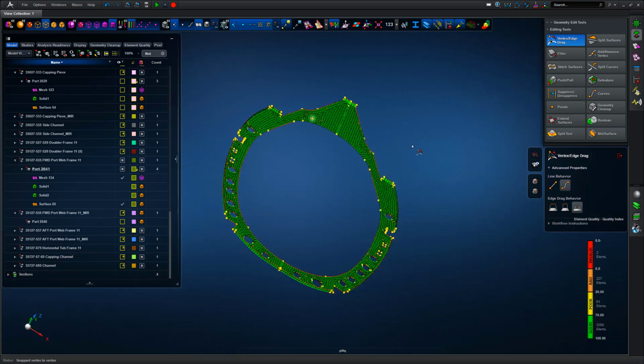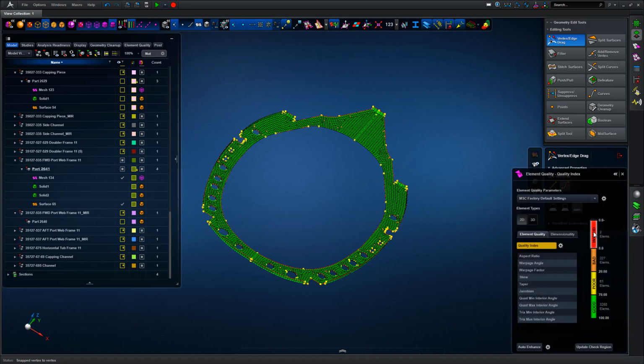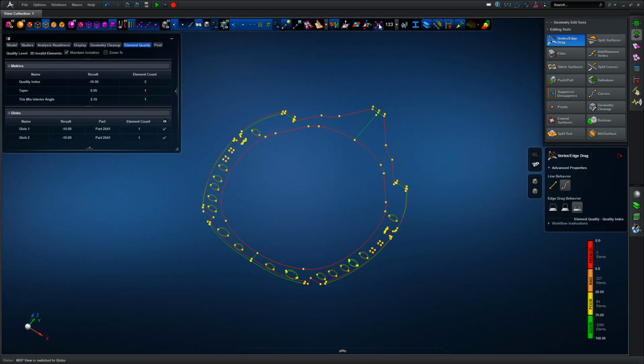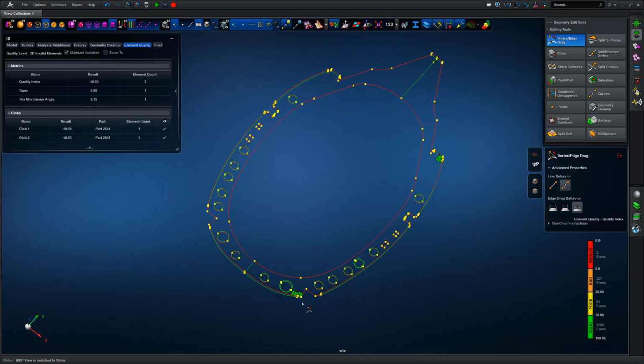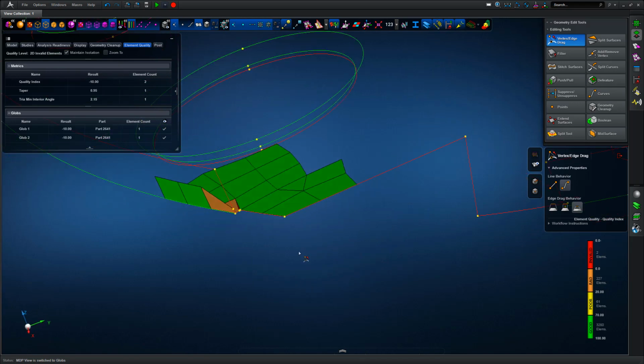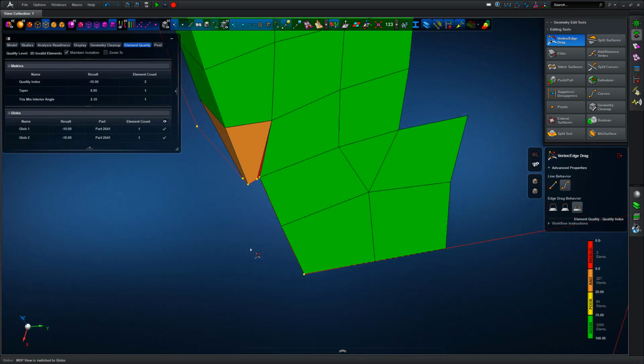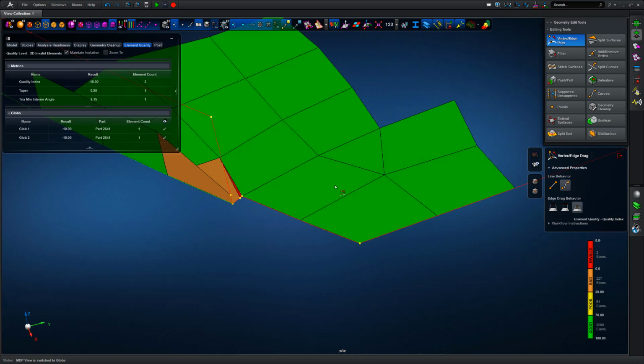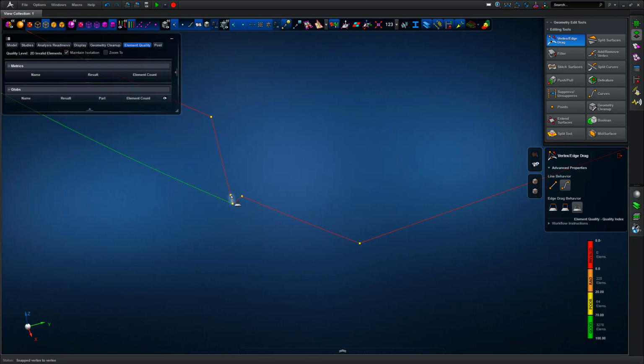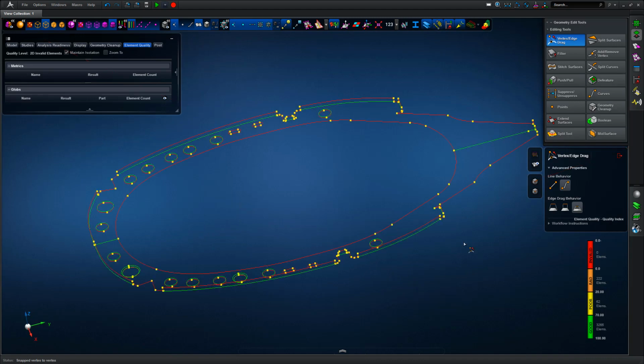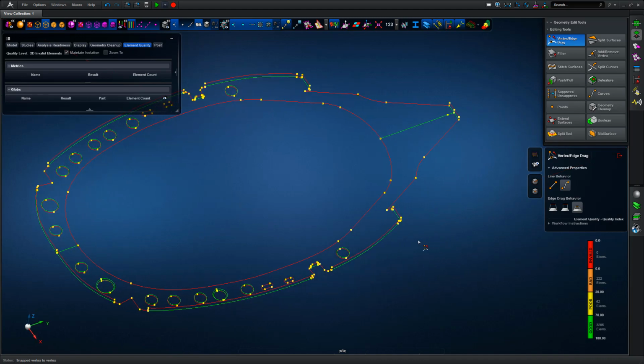So we repeat that for the areas which are obvious, and then we can isolate and enhance any other areas. Basically that posts to screen only the failed elements and the geometry which those elements belong to, and then we can again use the vertex edge drag. We can see that the mid-surfacing has created a couple of extra vertices where the original fillets would have sat. If you remember, they were there before we defeatured, so it's just left some vertices behind. So we do that defeaturing operation.